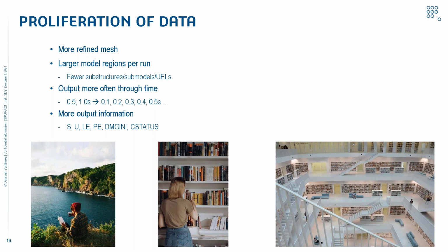You have more output information that you're requesting as well. So stress, displacement, logarithmic plastic, damage, status of contact. You can have more and more and more insights into your analysis, which is great. It's fantastic, but it's not always necessary, and it can keep your databases from performing optimally sometimes.